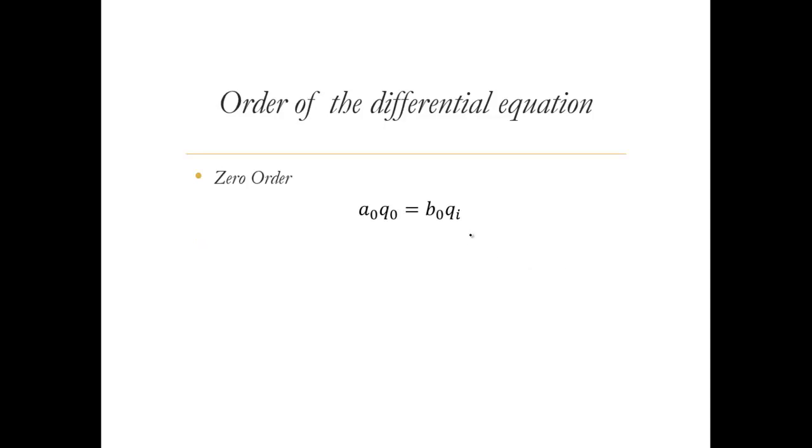We call this a zero order system in this case, or a zero order instrument also, where there is no dependence on the rate of change of the input, and there is nothing called rate of change of the output. So obviously whatever we are giving as input bears a linear relation with the output. There are some instruments, as we can see in the examples, where the output bears a linear relationship with the input, and it's very static. So this is more static, or you can say simpler in its expression.